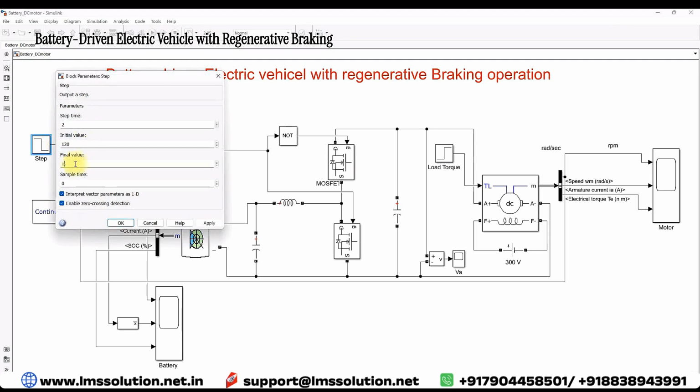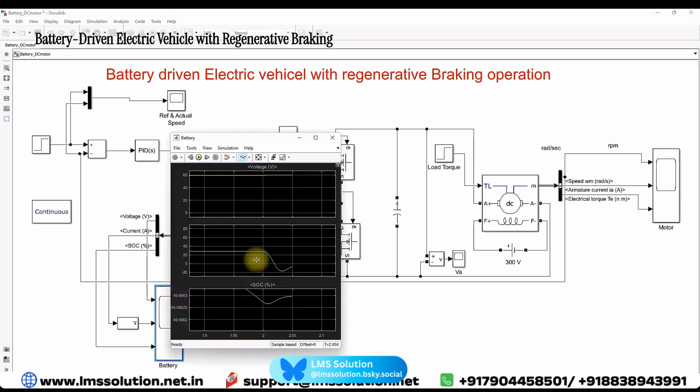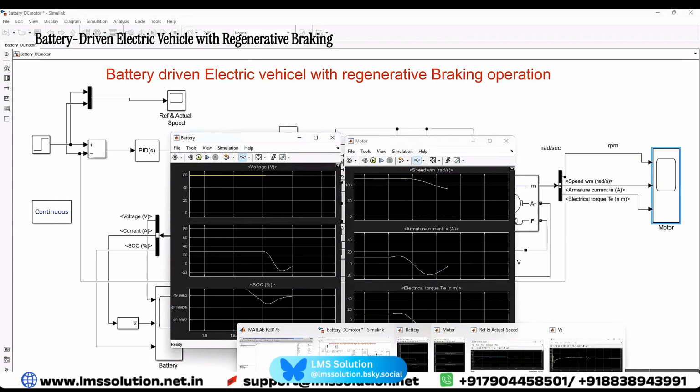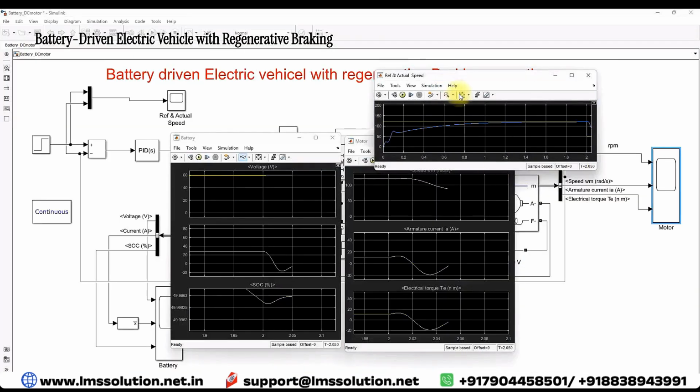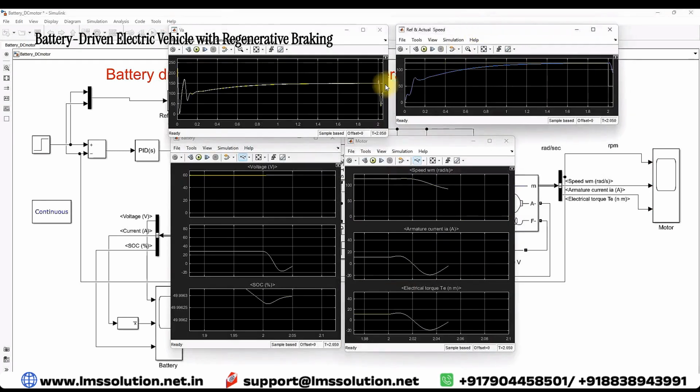Initially I'm going to operate the motor at a constant speed. I'm not changing any speed in this machine. I'm going to show the results of the battery voltage, current and SOC, and then the speed of the electric vehicle, or the speed of the electric machine or DC motor, the armature current, and the electromagnetic torque without changing any speed reference. I'm also going to show the tracking of speed, and this is the voltage across that machine. First I'm going to simulate this, and then we will check the results.